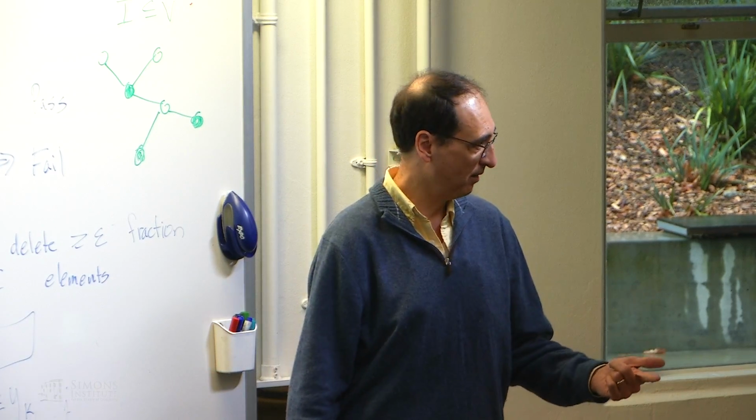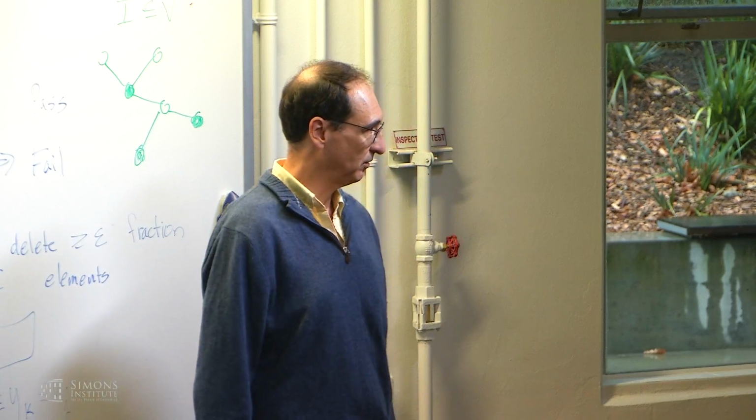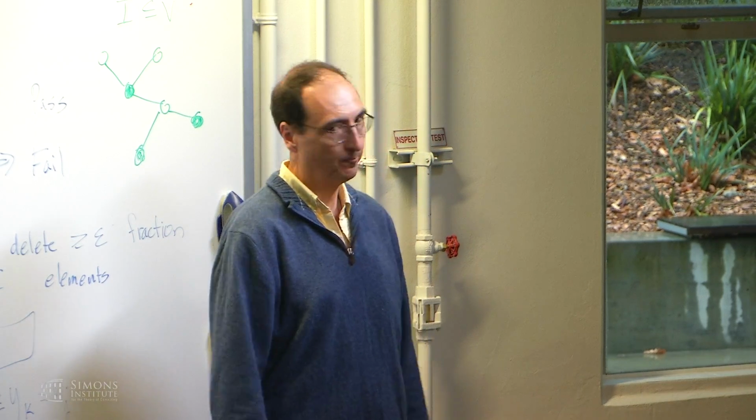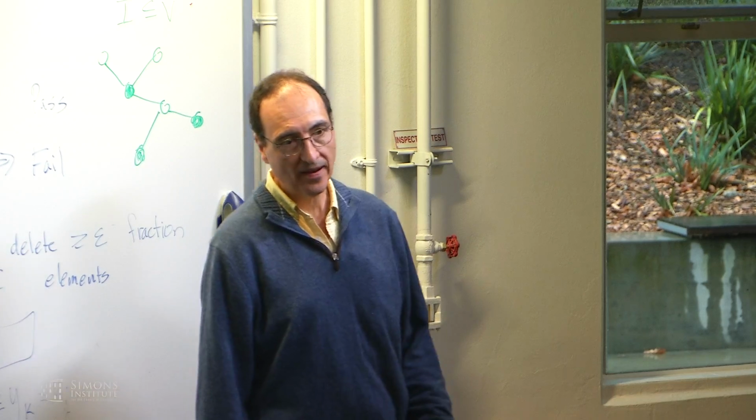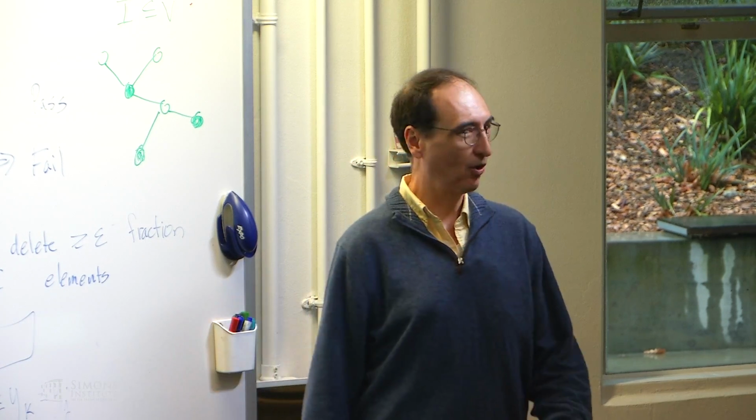And if you call the LQR command, linear quadratic regulator, it will give you the gain K that minimizes that integral. Done.